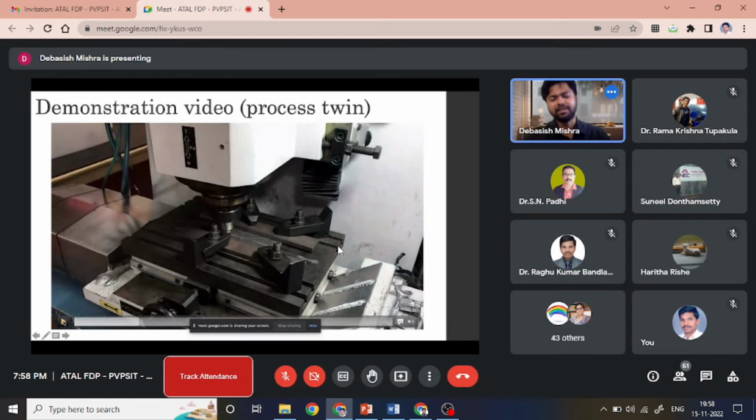So the material that has been kept here, these are two aluminum samples. The alloy is 6061 aluminum alloy, and this is an H13 steel tool, and we have fed the parameters to the welding machine in a way that a defective weld was obvious, and the online scheme is also working with this, and you get to see what happens.